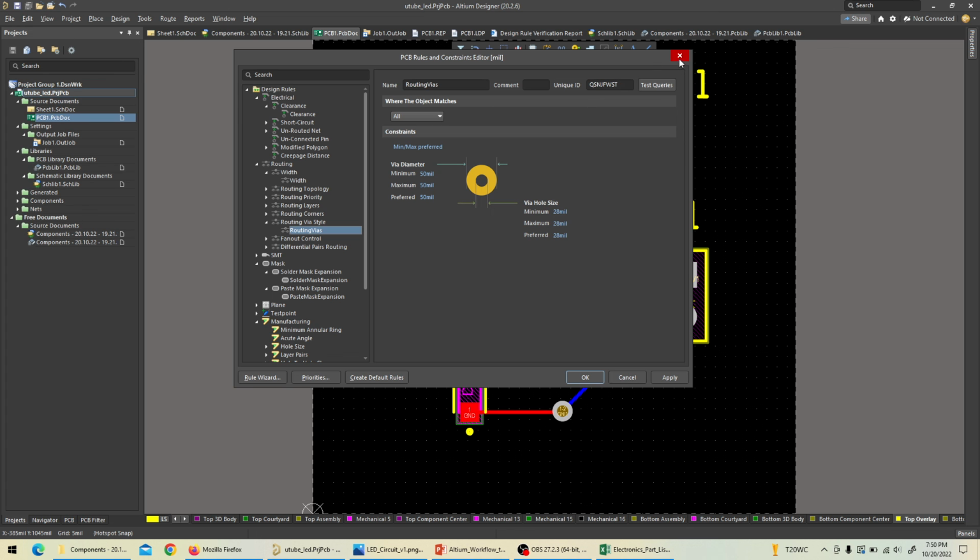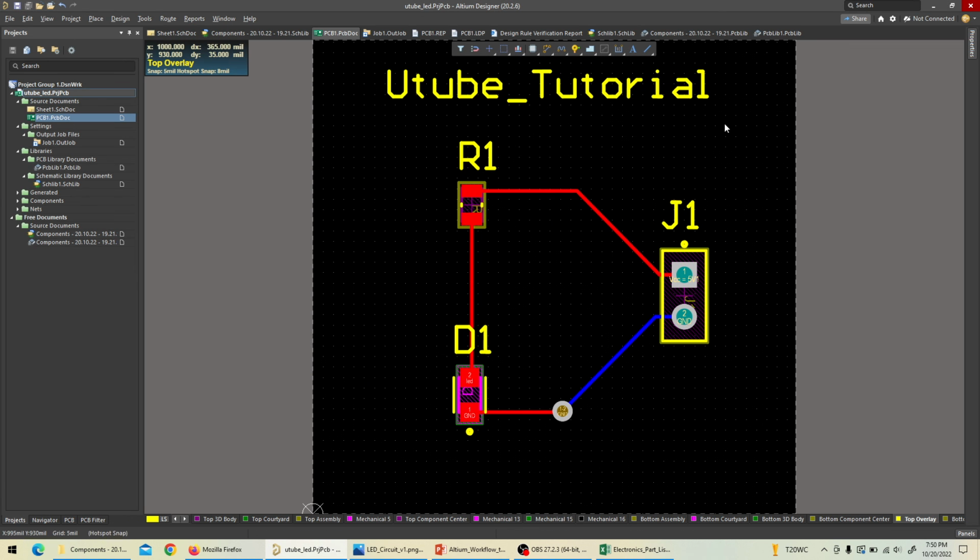Because normally when we want to put a PCB board and we want to make, you know, the four holes to put the screws in it so that we can fix it, I choose a via of a very large diameter, of my screw size, so that when our board comes back, it has those holes and I can fix that PCB.